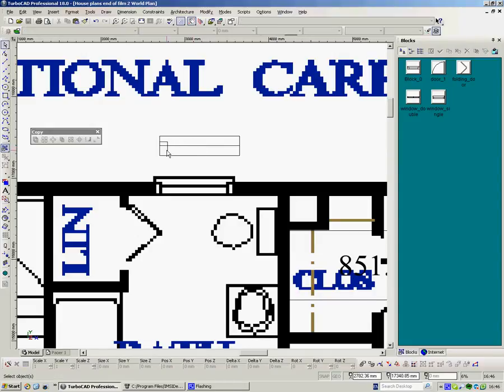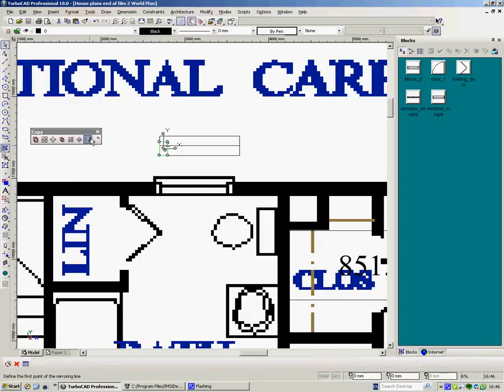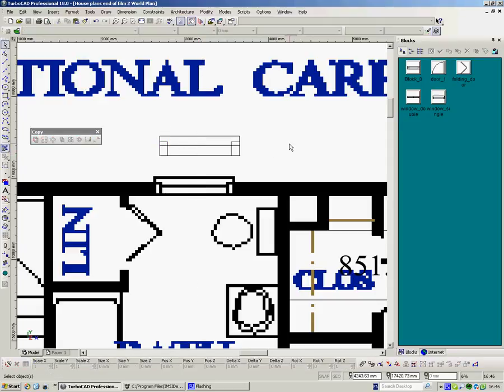I now want to mirror this rectangle here. You see one over this side, so it's a mirror copy. I'm going to use the rectangle as my guide, so I'm going to do M for midpoint here and M for midpoint there. There it is down the end.